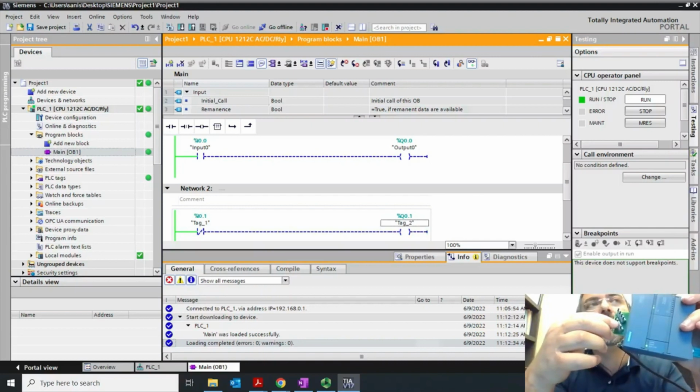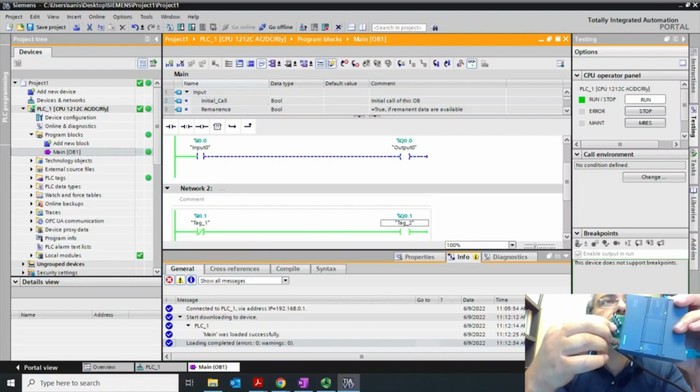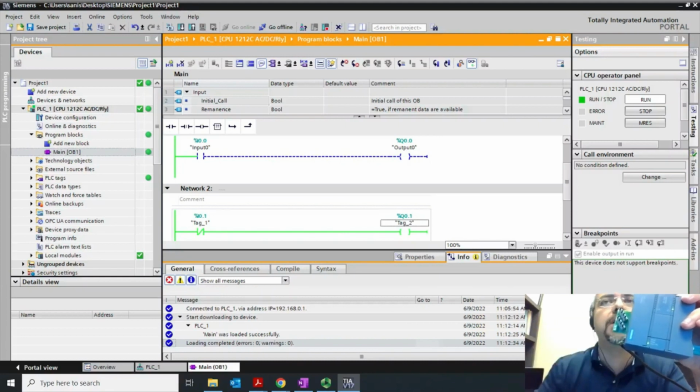Okay, so I'm touching this second toggle, which is connected to I1, sorry. So see, I1 right now is 1. This is normally closed. So whenever it is 0, normally closed, it's closed, it is on. Even you see the IO LEDs, which are on, and also you see this from here.